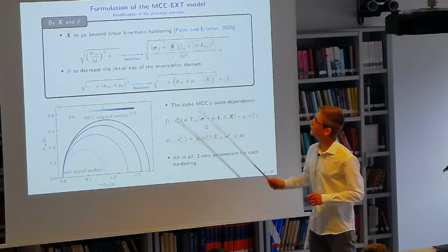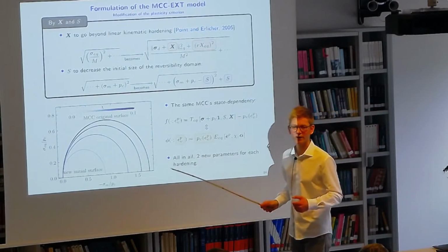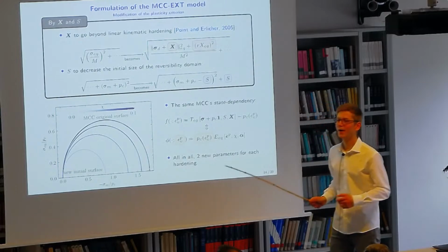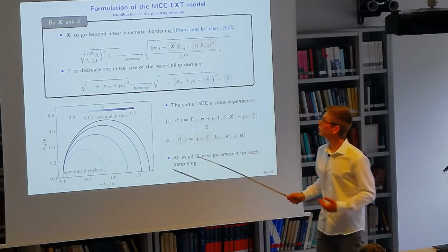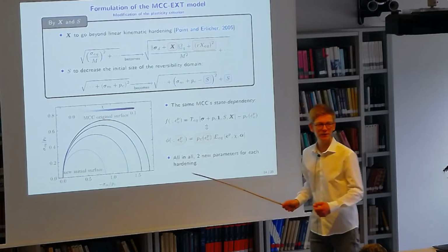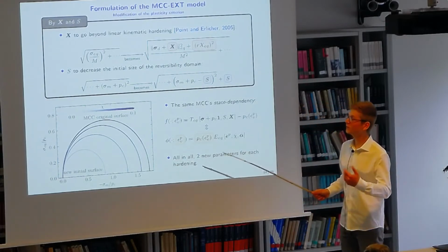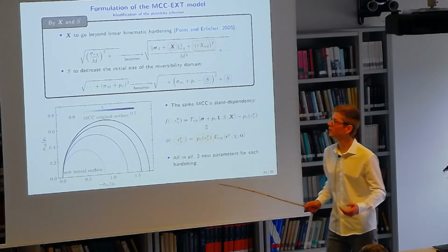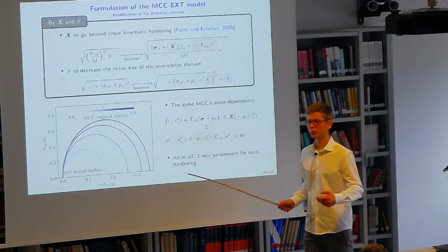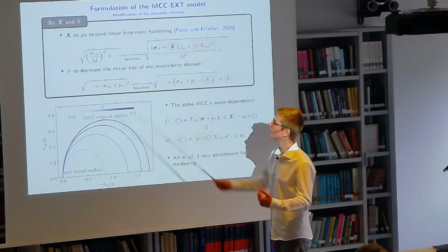Here, in the first term, X would play like a back stress as for kinematic hardening. However, the other term, which involves a new parameter R, allows us to introduce nonlinearity in this hardening. This is quite interesting and compulsory if we want to be able, as for the Cam-Clay model, to predict an ultimate state for which there is no evolution of the equivalent stress.